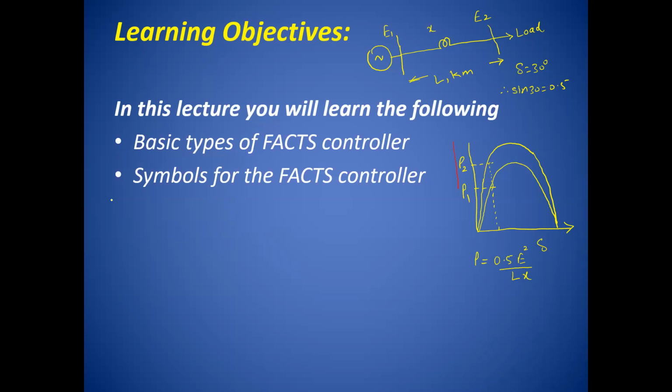Hence, it is not only to enhance the angle and power handling; we have to understand the transient condition and steady state stability of the transmission line. We cannot operate at more than 90 degrees, isn't it? Otherwise it may come out of steady state stability. Similarly, we have to keep a sufficient margin for transient conditions, because transients are very fast and the quantum of the disturbance or perturbation is very large. During that disturbance, our transmission line or the power system should not trip, or have cascade tripping, or come out of synchronism, isn't it?